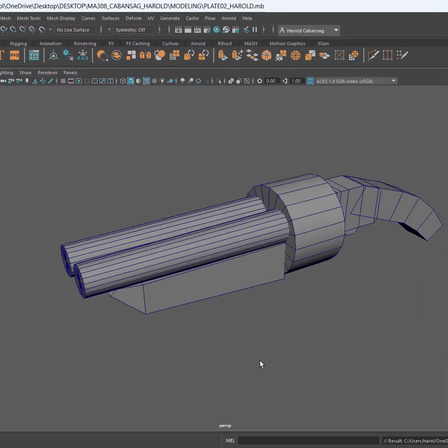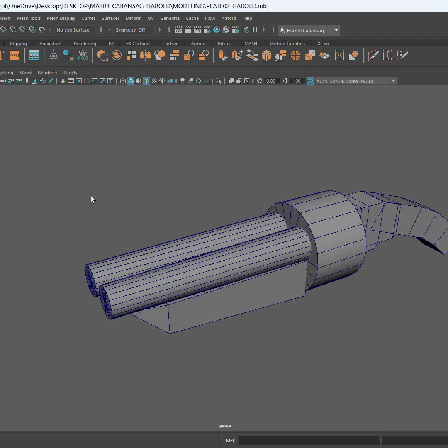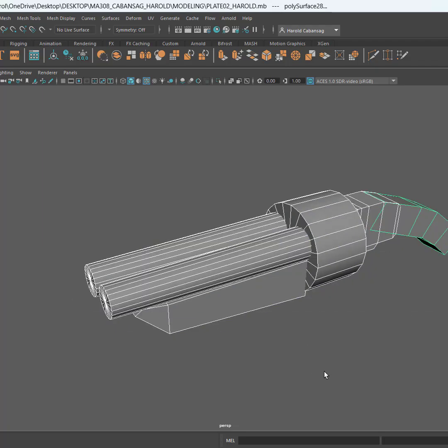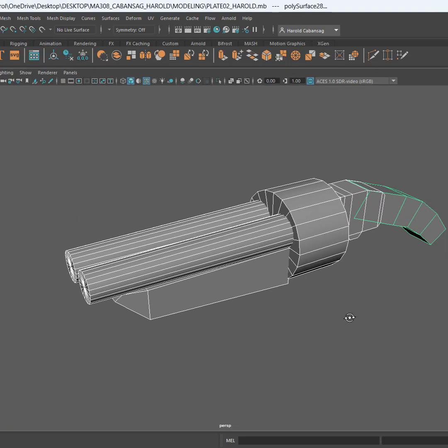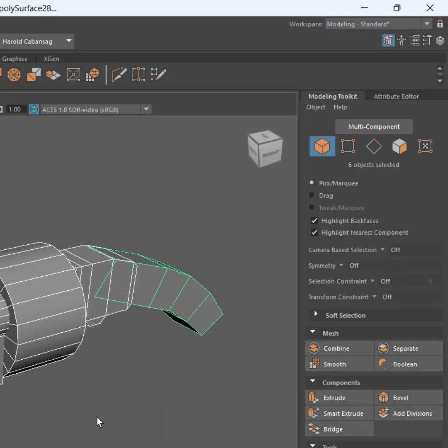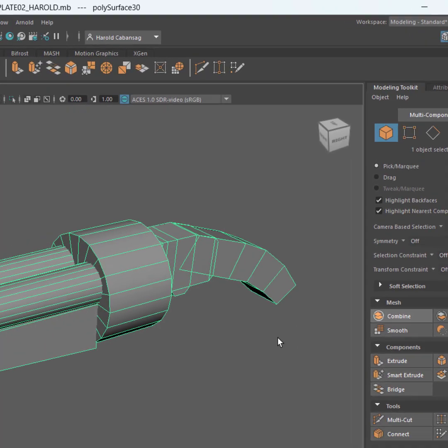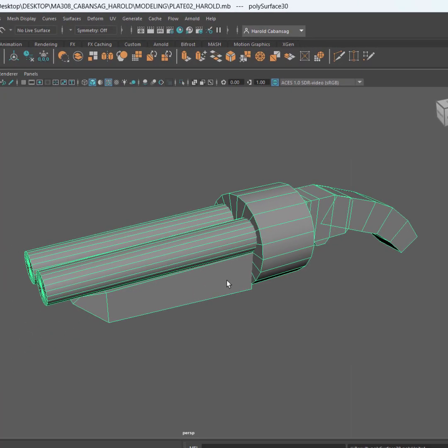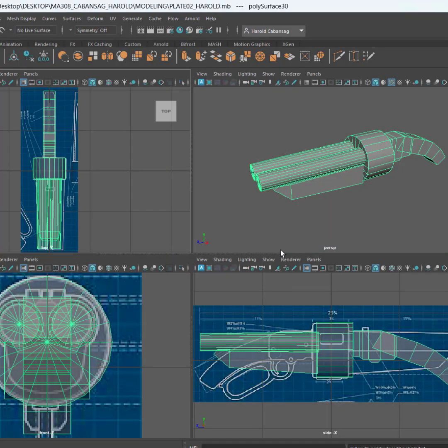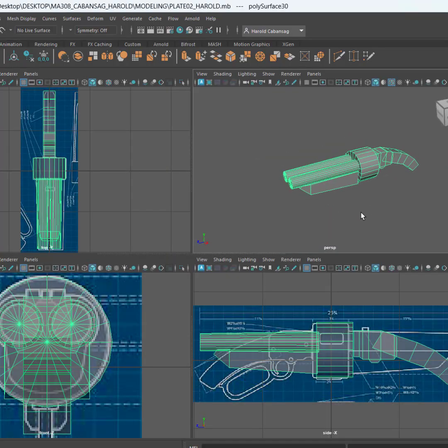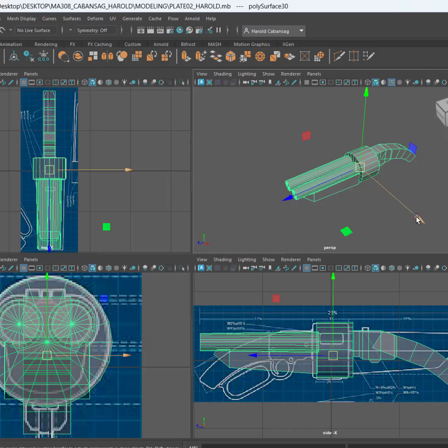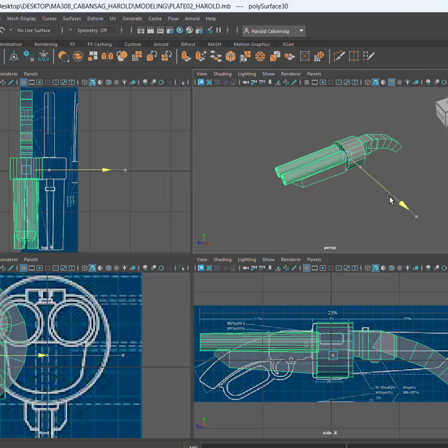And now the next thing to do is I will select these and create an in-file backup. So I'll select all of these initial objects that I have created, go to my modeling toolkit, choose combine, click that, and then tapping spacebar, I will push it away from the references for now.